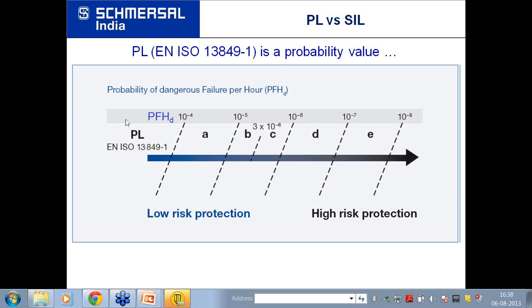Mr. Ayal Lakshmi Narayanan has asked, do we get wire break information? If you are talking about wire break information or short circuit information, yes, you get information about wire breaks, open circuits or short circuits if you have intelligence in the system. That means if you have a safety relay or electronic device which has that kind of intelligence, you get these features available in the system.